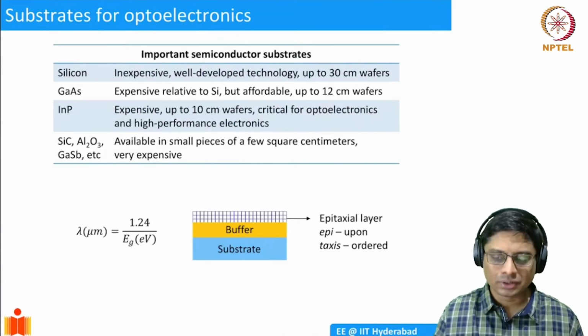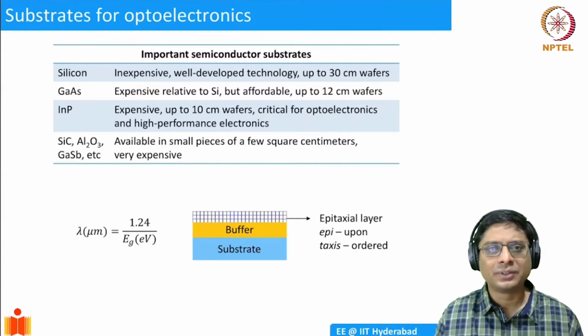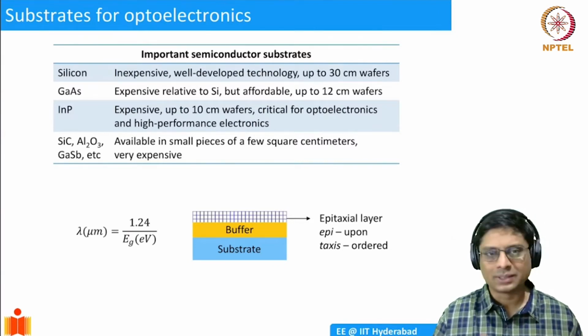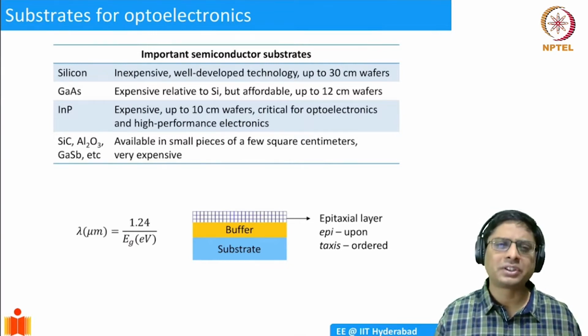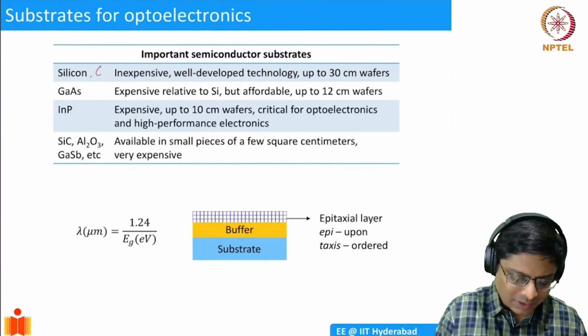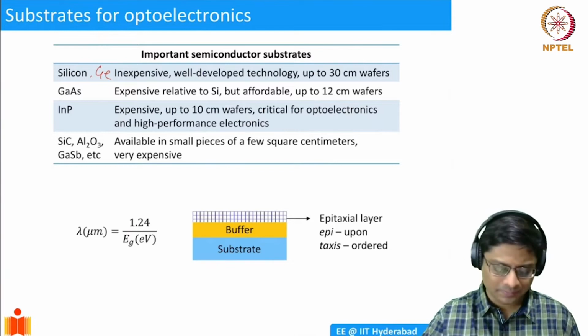Okay. So the reason I'm discussing this is, whenever you have semiconductor devices, we want very, very pure materials and large sizes. For example, silicon, we can purify it to 9N levels, and then we can have wafers which are about 1 foot, 12 inches in diameter. Okay, and this is a very, very well developed technology, relatively cheap nowadays. Okay, so silicon is easy, and even germanium is available quite easily. It may not be the same diameter, but you can get it quite cheaply.